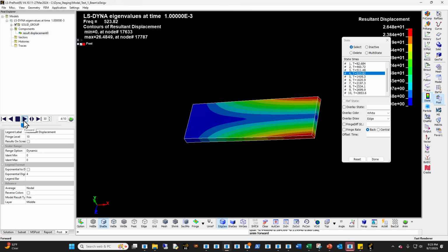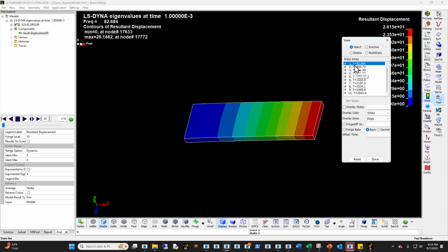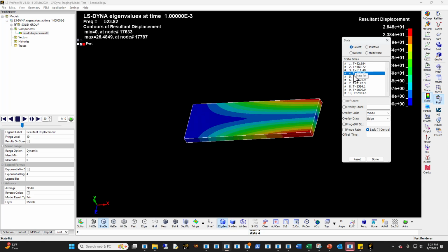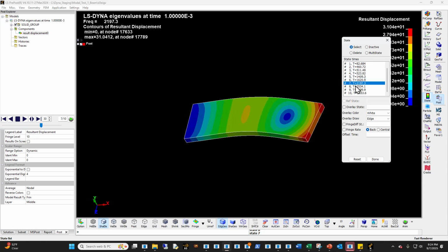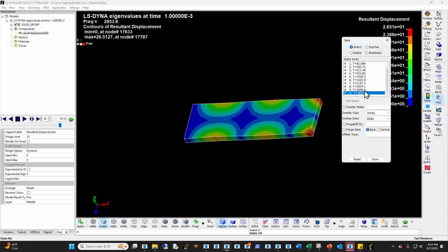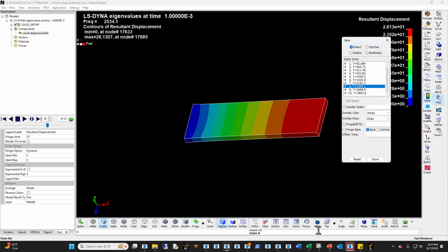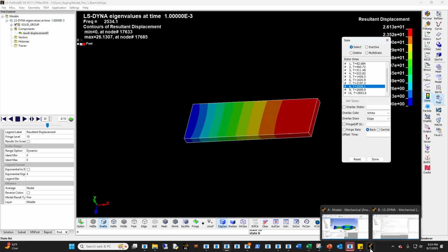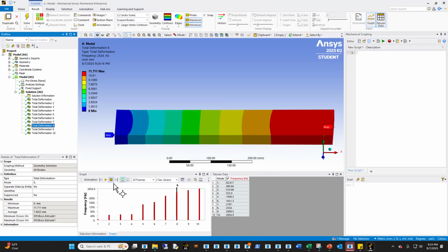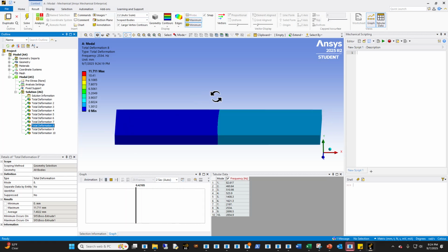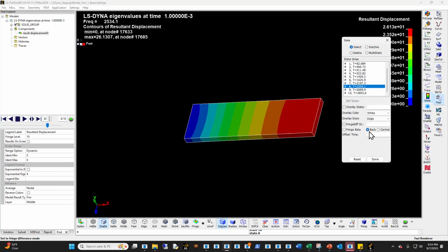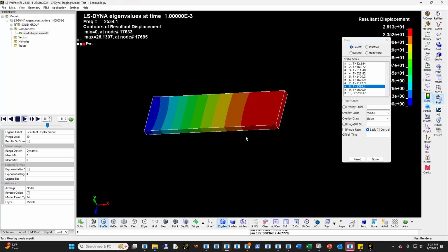And what you can sort of see here is that you have different mode shapes, right? 1, 2, 3, 4, 5, 6. And they're exactly the same mode. So for example, mode 8 over here should be the same thing as mode 8 over here, right? So it's an extension mode. Okay, and even the scaling factor might be different, but that's just from your eigenvalue problem. It's just a scaling factor in that regard. Okay, so you can see you get basically the same results.